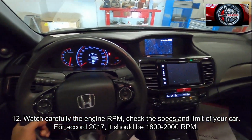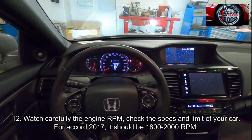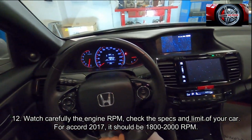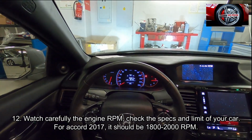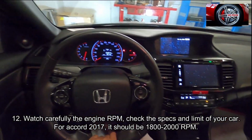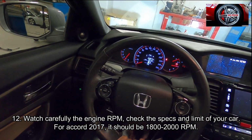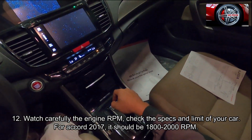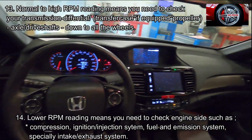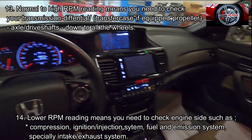Okay, so this means the engine has enough power to accelerate, but the problem is maybe what we suspected is the transmission, because the engine is obviously producing enough power to accelerate the car. So the next thing to do is check this DTC using scanner.